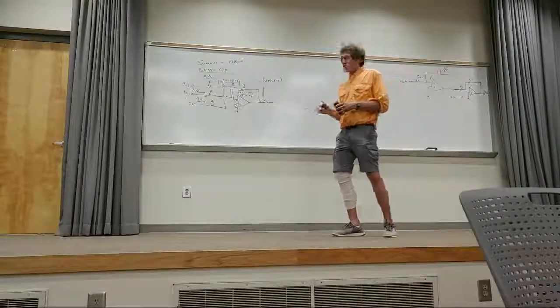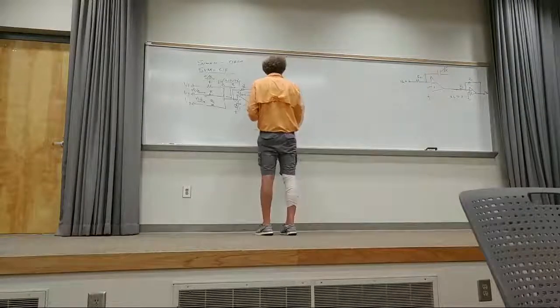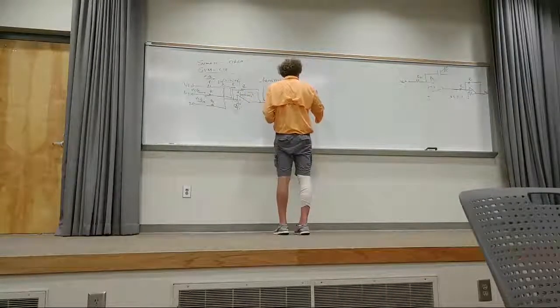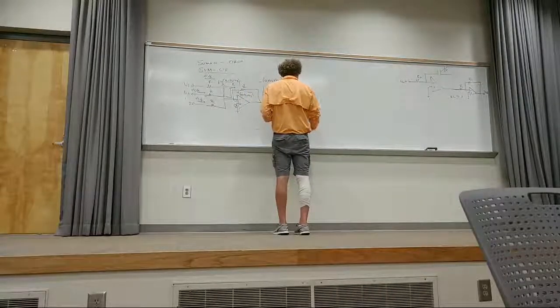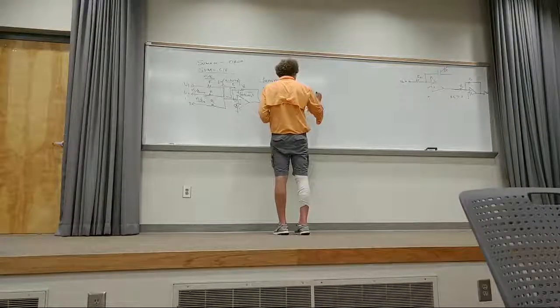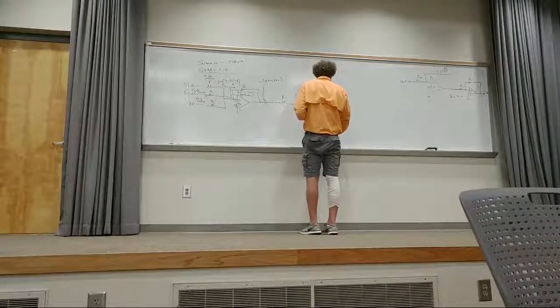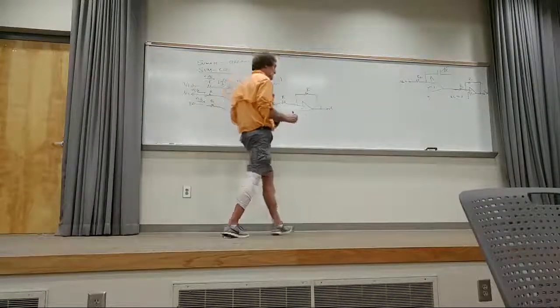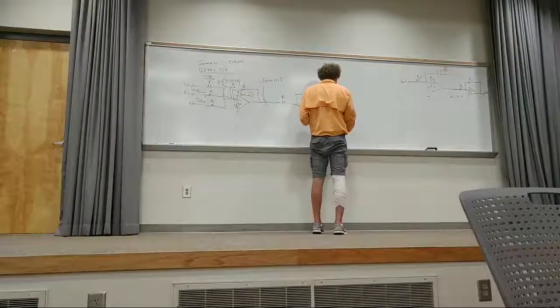Put an inverter. Yeah, just do a simple inverter. Just put a resistor here, R, another R, then put it into a negative, positive, ground that one, take that out, and that's V out. And that's your V in, and V out is now equal to V1 plus V2 plus V3.